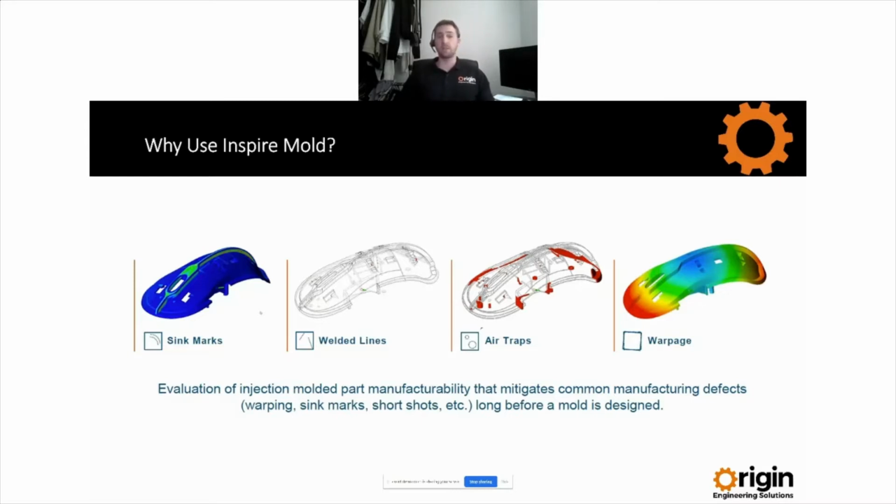Another reason you might use Inspire Mold is to guide you on the best method: gating locations, the best place to put cooling lines, and so on. So it can guide you on how to build your actual mold tool as well. Lastly, you may use it to remake existing mold tools. You might want to optimize an existing mold tool, so you might want to run it through an analysis tool. Maybe you are getting issues with parts that you haven't run analysis on, so you might want to run an existing mold through the software to see if you can improve on the design.